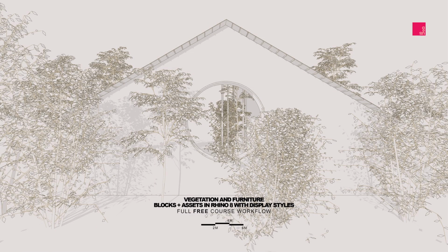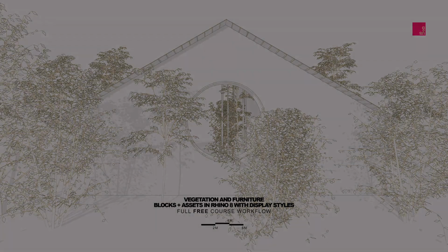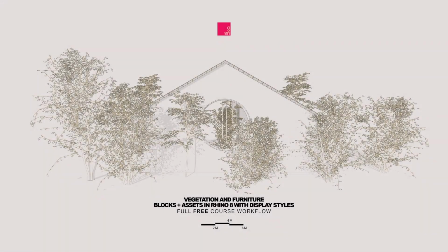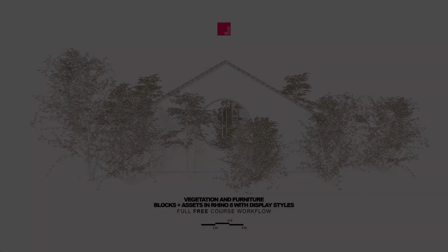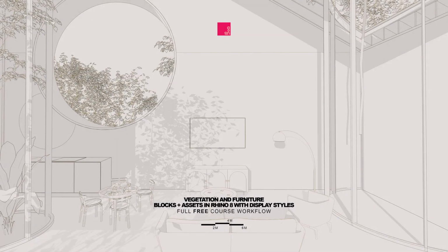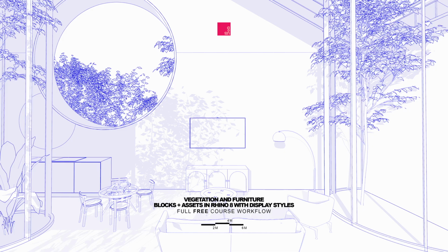Just one quick note, you can do extract wireframe or dupe face border if you wanted to, but that only works well if you're going to make 2D in a single view and clean up the lines later. Again, I like to do everything in Rhino. Sometimes I take things to Illustrator and I'll make separate videos about that, but these are for people who want to do almost everything in Rhino. I do my layouts in InDesign and annotations in InDesign.